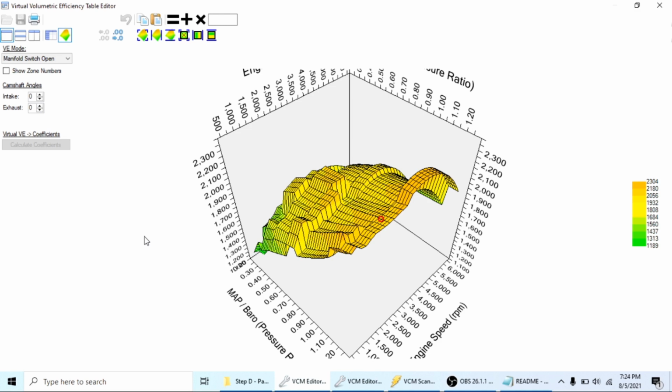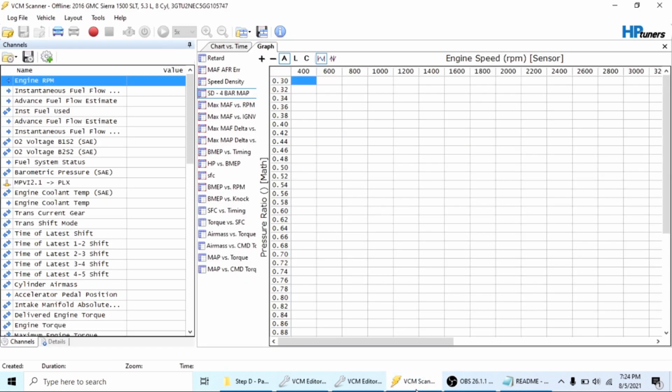But since it's kind of a hybrid at this point, the stroke is the same on all these Gen 5 engines. Well, that's an LT3, LT4, LT1, LT6. They've got the same stroke. It's just the bore that's different. And so outside of the camshaft and the bore being a different size, it's getting close to looking like what an LT4 is. And obviously some other details.